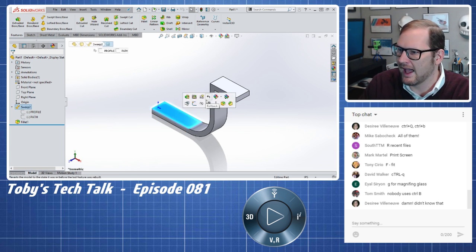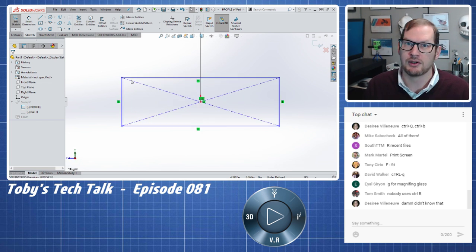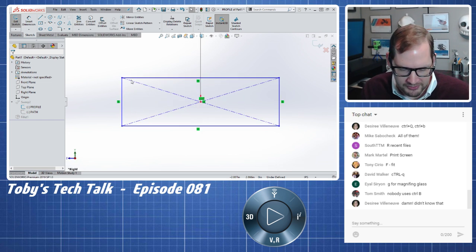Or a lot of times I get into edit sketch mode, and once I get into edit sketch mode, I'll just press Control 8, which drops me right into a normal-to view and zooms me in on the sketch.